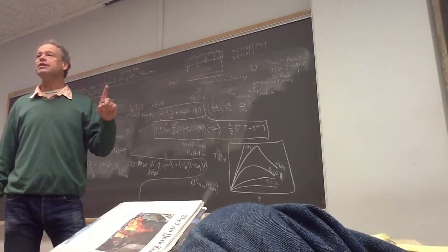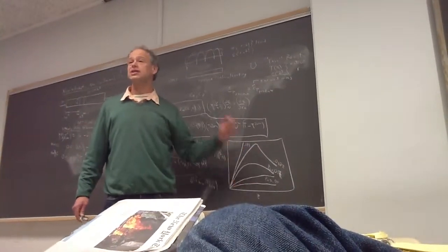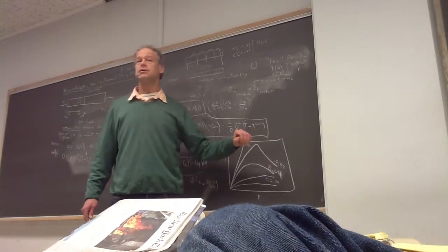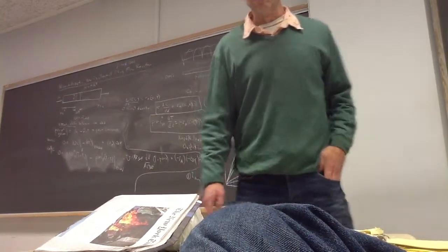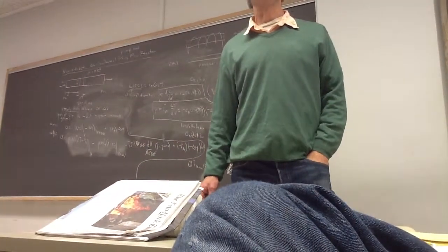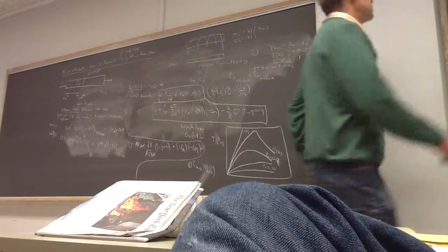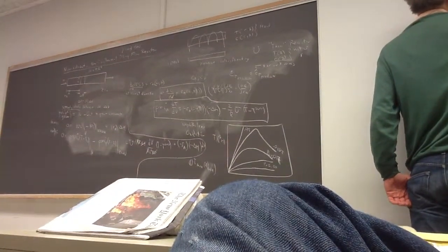Tmax. How high Tmax is and where Tmax is. I need to know where it is because that's where I have to put the coolant. And I want to make sure that Tmax is below the maximum allowable. So we're going to come up with a method to estimate Tmax. And to estimate Tmax, we're going to have to think about the physics.